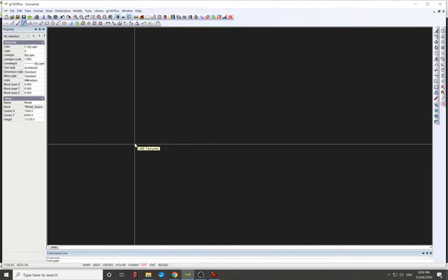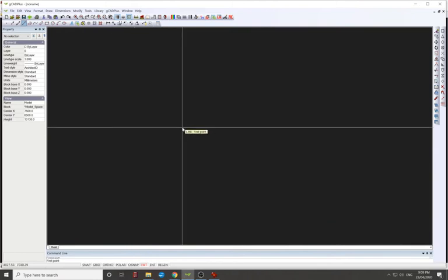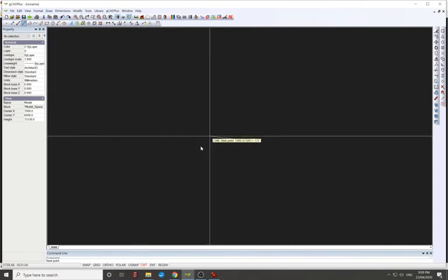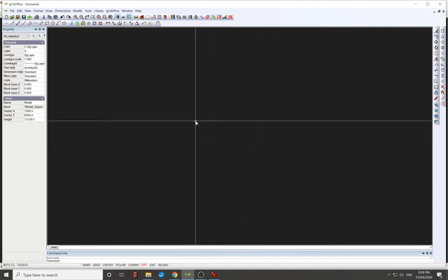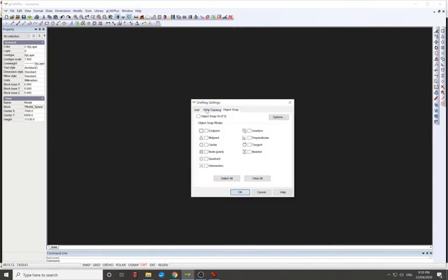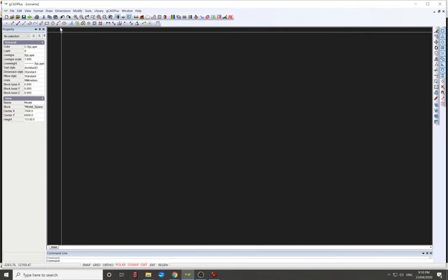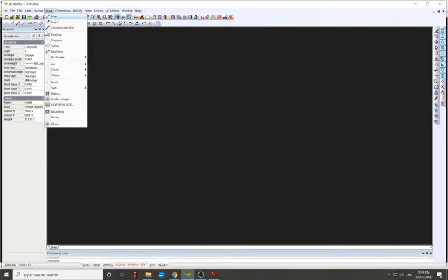The first measurement is 6,515 millimeters. So we go draw line, but we've got no snap on or orientation. This is why you right click, draft settings, polar tracking, turn that on, object snap. I click them all. You can go snap on. That sort of stuffs me up sometimes. For now, we'll just leave this line.